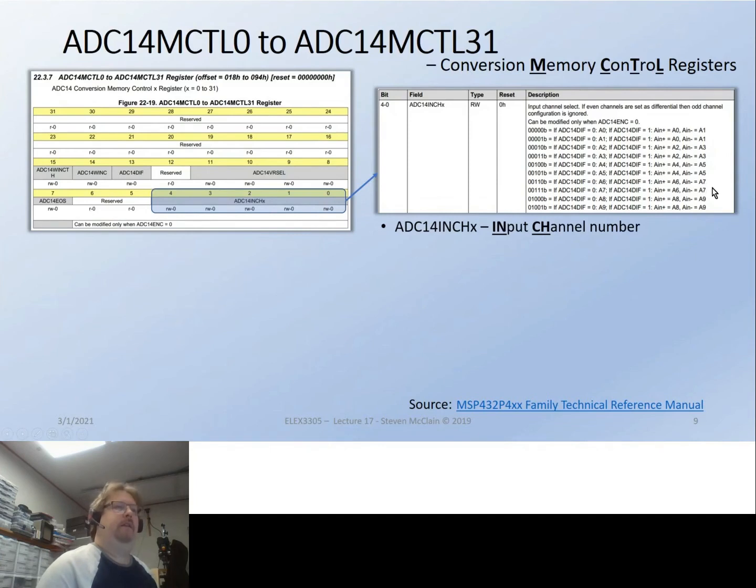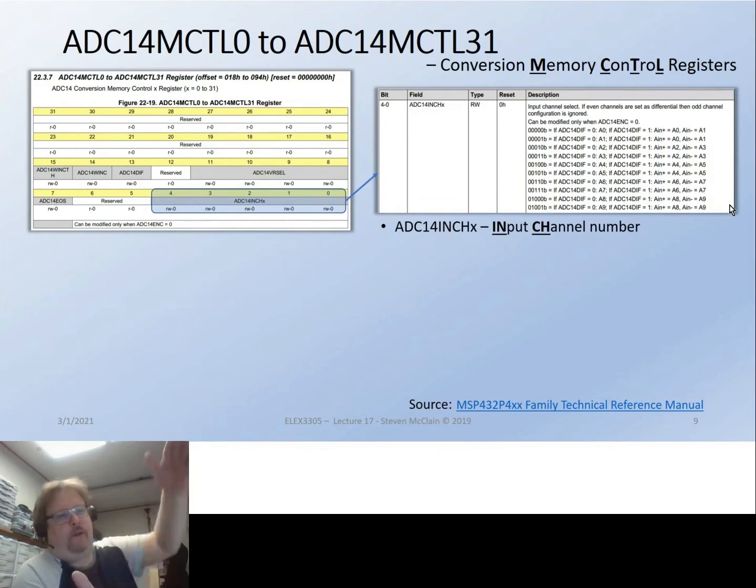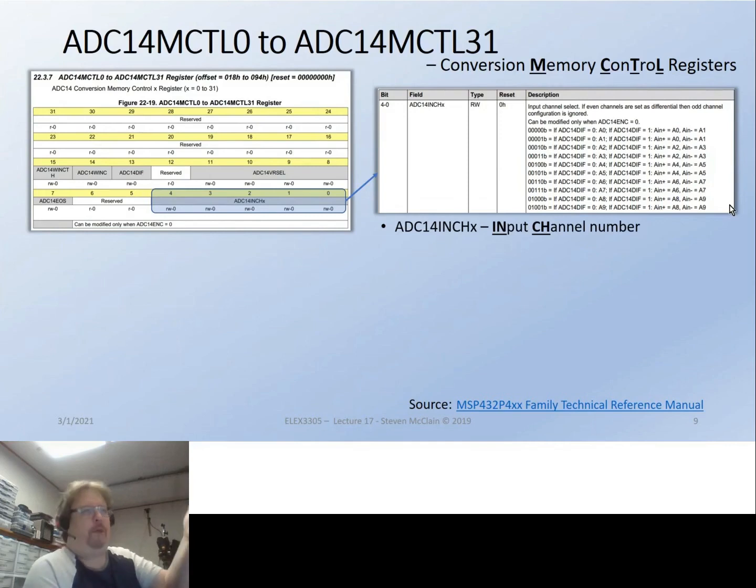You're losing me here, man. So the inputs to the converter, sorry, I know I'm babbling here, going around in circles. I don't have a good picture for it. The input to the converter, the voltage that you're actually going to convert, can either be single-ended or differential. If it's single-ended, it's with reference to ground, or with reference to the negative reference in this case, and just a single voltage on a single pin. So everybody has the same ground and your voltage is referenced to ground, period. So you got one signal, one wire.